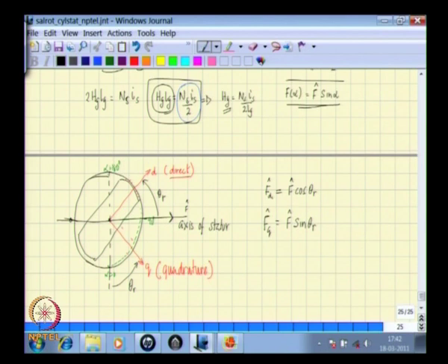So, we have now arrived at expressions for denoting the peak value of the MMFs acting along the d and q axis. We now have to define the spatial distribution of this. You see that the MMF generated by the stator is spatially distributed, that means as you travel around space, what is the variation of MMF that you would encounter? That was given by this expression f hat into sin alpha. Now, by resolving these two expressions describe the peak, and therefore, what would the spatial distribution be?